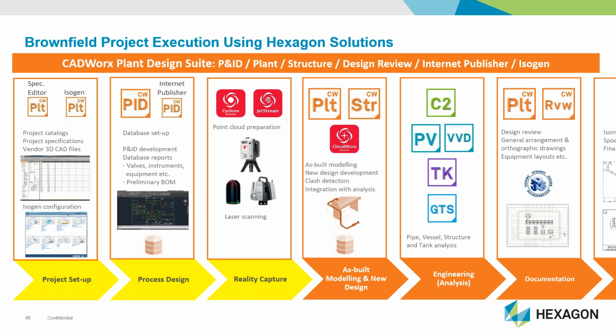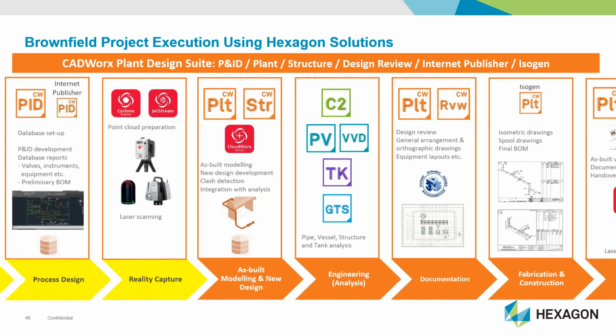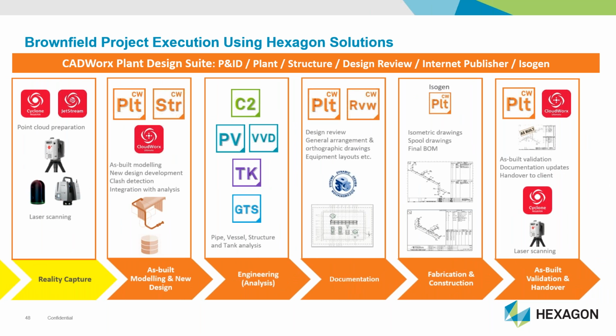Okay, so let's take a closer look now at how CloudWorks and CADWorx are actually used together to execute the typical stages of a brownfield project shown here, which starts with reality capture and ends with the handover of data and documents to the plant owner-operator. Now, at this stage, we've already set up the CADWorx project environment. We've taken delivery of the reality capture data from the supplier or from our own scanning team if it's done in-house, and we're ready to start using the point cloud data to design the changes that we're going to make to the plant. Now, how we use the software, of course, depends on the project scope.